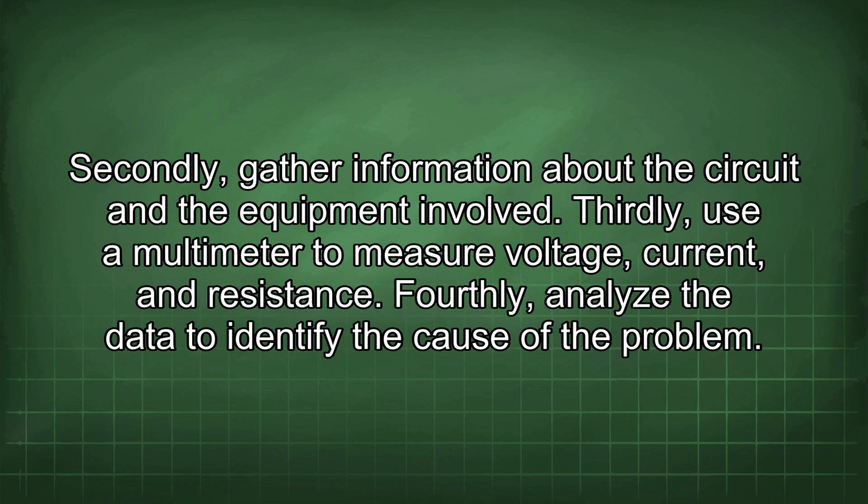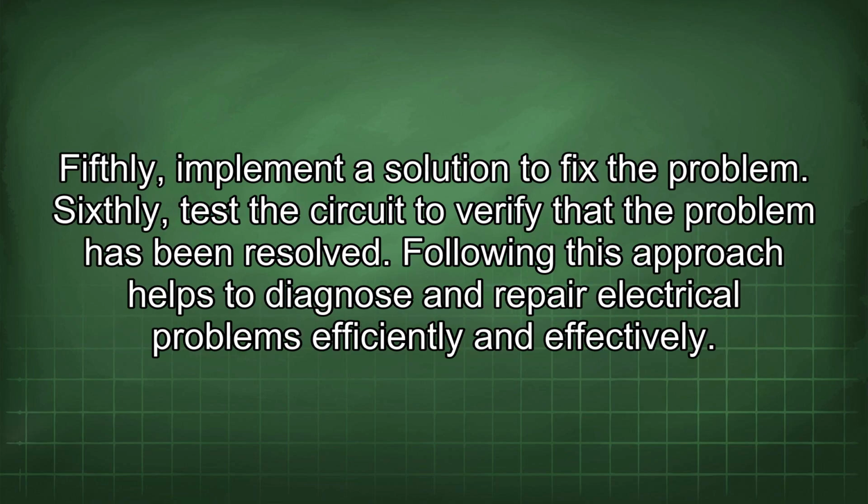Fourthly, analyze the data to identify the cause of the problem. Fifthly, implement a solution to fix the problem. Sixthly, test the circuit to verify that the problem has been resolved. Following this approach helps to diagnose and repair electrical problems efficiently and effectively.